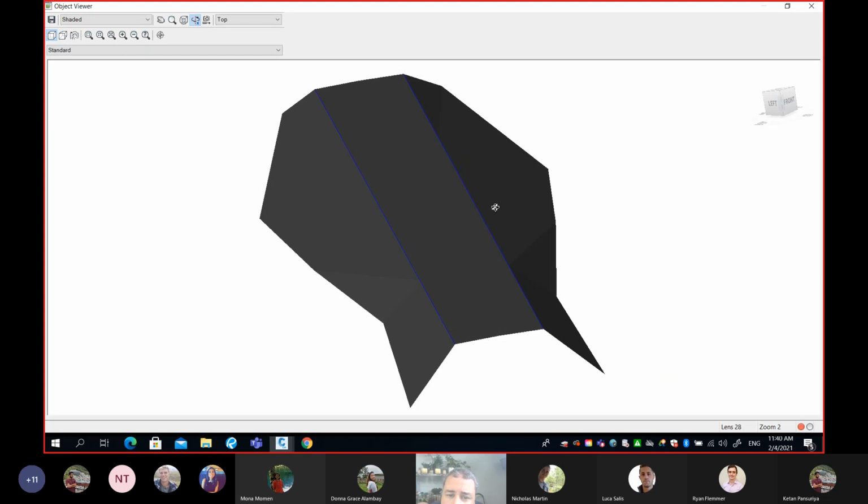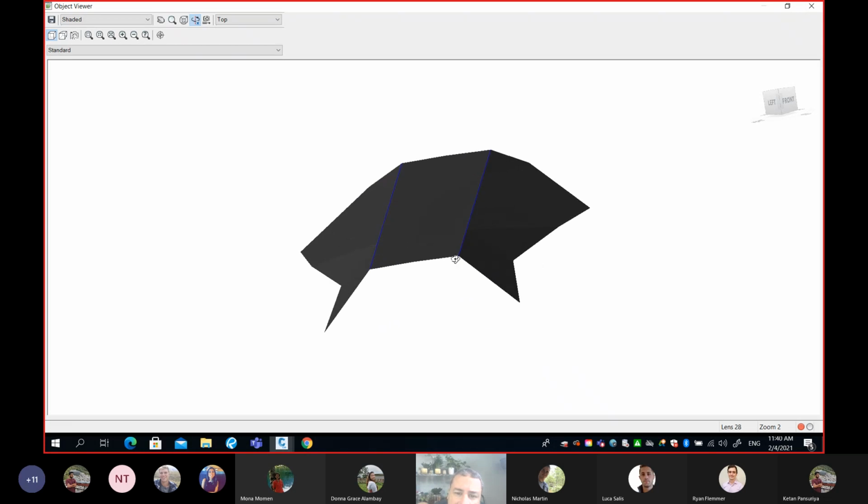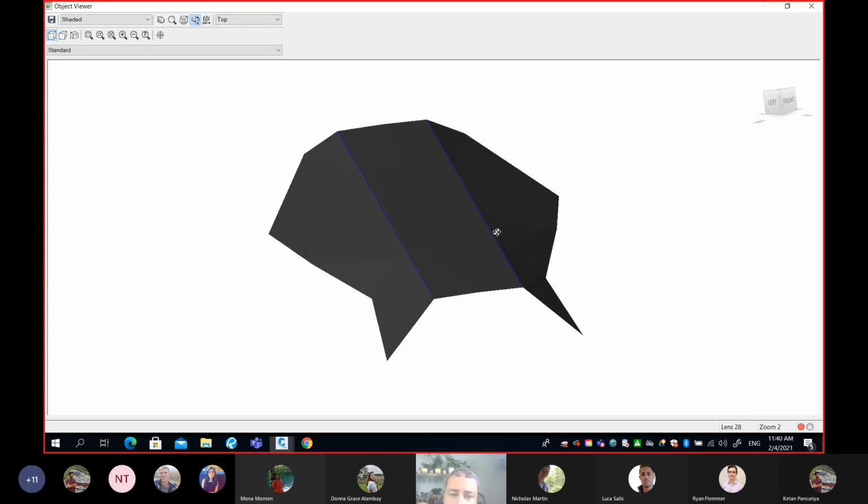So there is no problem, because what I did is I drew those 3D polylines on these points. Then I added them to the surface definition. And what this means is: do not cross me. Make some triangles right of me, left of me, but never cross me. And you can see my road is beautiful. You can see there are 2 lanes of the road and there is side slope. I'm hoping that you guys understand by now the importance of break lines. Break line is one of the most important things in surface definition.